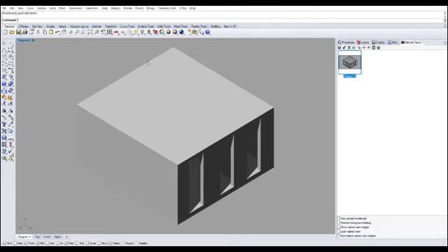This window is called the V-Ray frame buffer, by the way. So when it finishes, it should tell you. If you would like to know when it finishes, all you have to do is click on the Render V-Ray Frame Buffer. Here it is. So there you have it, 100%, it's finished. That's my first diagrammatic render, which is basically a white base model.